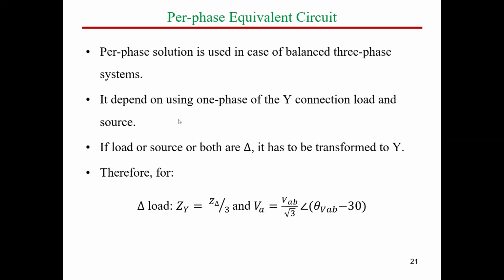What's the meaning of per phase equivalent circuit? Now, guys, since we will have balanced three-phase systems in our circuits, we don't need to draw the three phases every time. We can just replace the circuit by a single phase because it's going to be just repetition for the drawings and calculations.